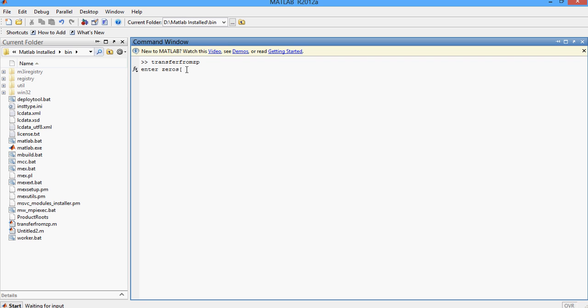Let me give the zero as -3 and the poles as, you need to give the poles as a column. It works even if you give it as a row, but if you give it as a column it's going to be even better. And to give it as a column, say you have 3 poles to give for the transfer function. You need to separate them by a semicolon. Say you gave 2 semicolon 6 semicolon 7. Even if you don't give it, it works most of the time, but better you give it this way. So you got the P.